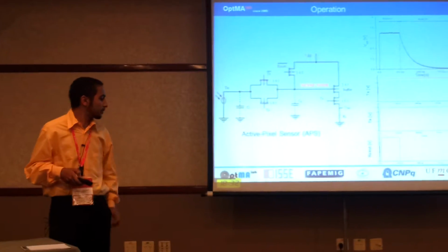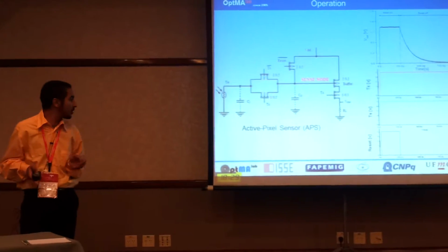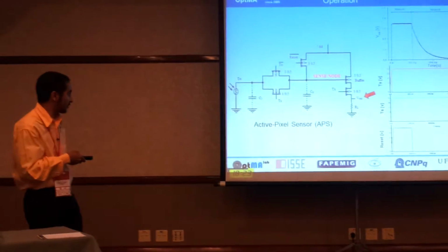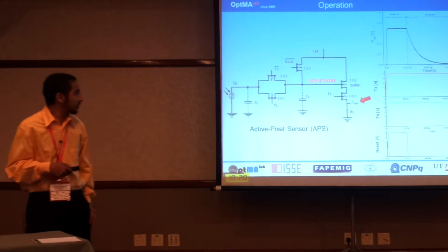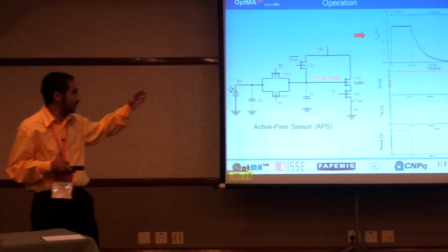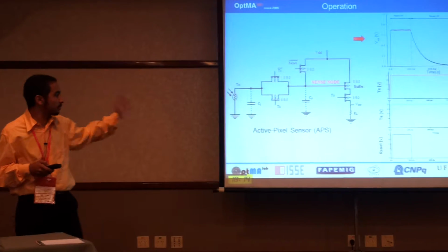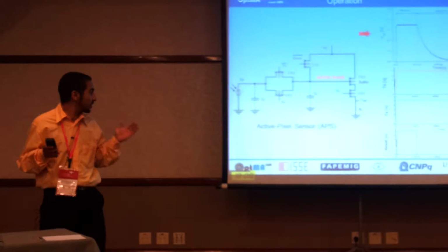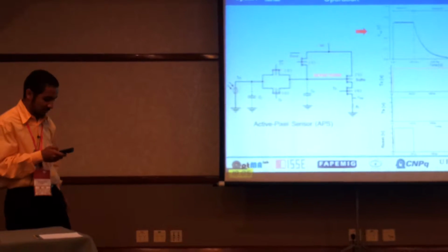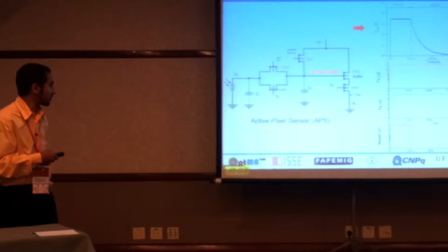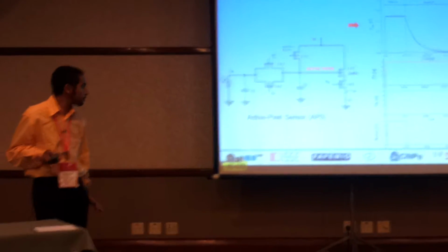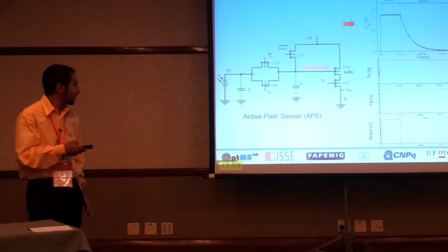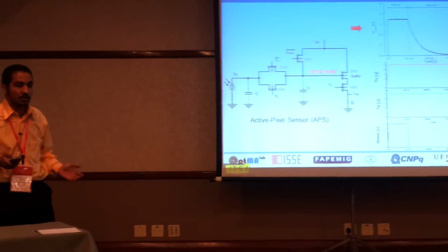The modeled microelectronic circuit used is shown in this scheme, and its response is read on the out node. A typical response is plotted on this graph of voltage versus time. The general operation of this circuit is: the transistor reset and transistor PS work as digital switches, the transistor PX works as an analog switch, and the transistor buffer works as a common drain amplifier.